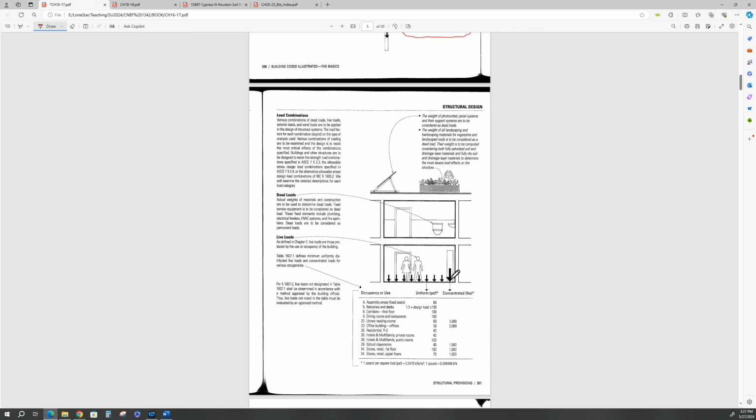All right? So a concentrated load is a heavy load that's not going to move. It's just something sitting on the structure. Could be a giant piece of equipment in here that's anchored to the foundation floor. Is a concentrated load. And then your uniform live loads would be people in here walking around. You might have 20 people in here at a time, maybe have one person. But the concentrated load is calculated by the weight of the equipment and dynamic loading on the equipment.